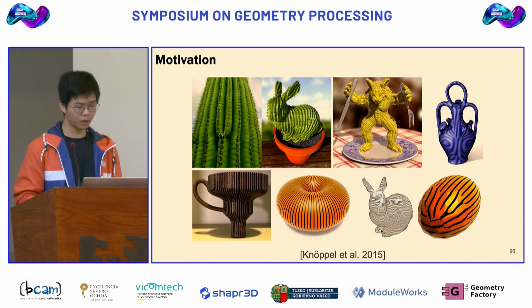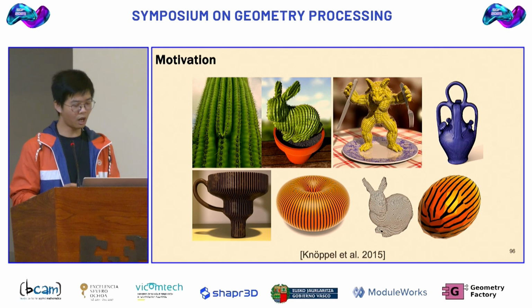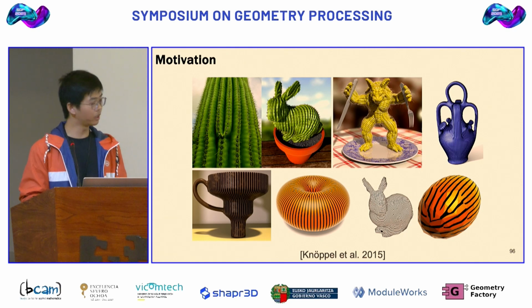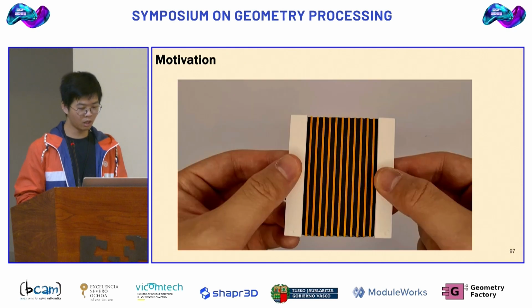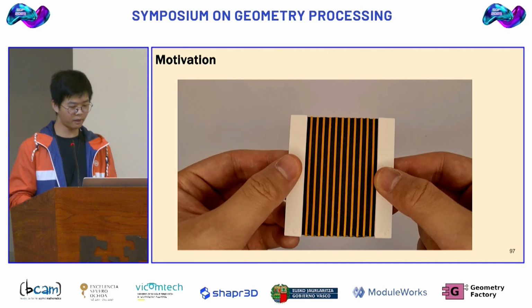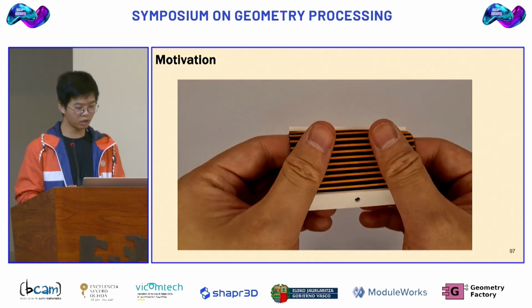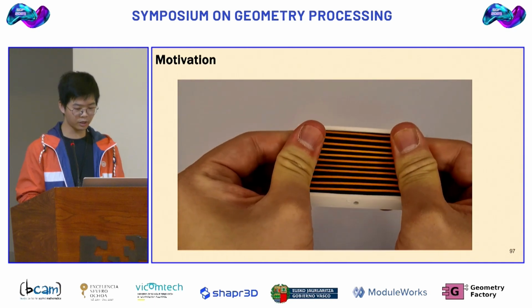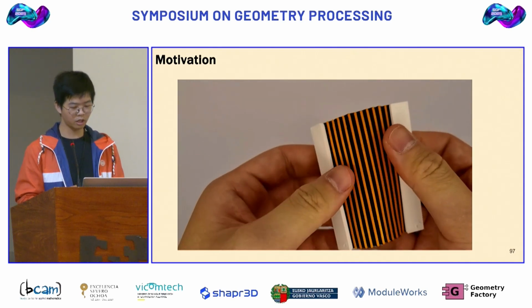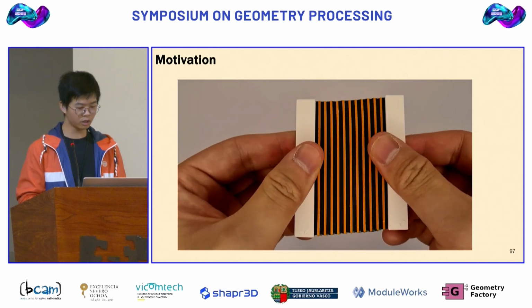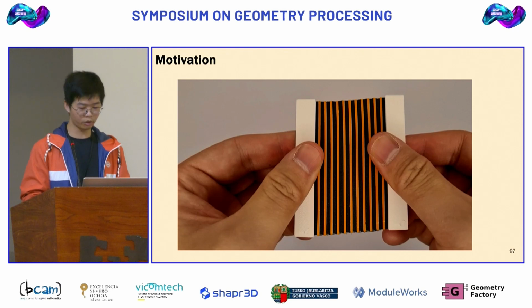In the graphics community, we have developed powerful algorithms capable of computing textures of stripe patterns on arbitrary surfaces. One area that hasn't been fully explored is the ability to control the macro-mechanical behavior of structured surfaces. In this regard, stripe patterns provide an interesting design space for structured materials. By 3D printing striped patterns on textiles, the created material can exhibit quasi-inextensibility in one direction while being compliant in its orthogonal direction.